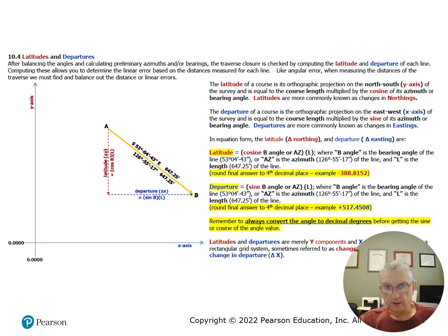So, here's just a good example. Don't round it too far. He's got, final answer rounded to the nearest 4 decimal places, and typically we'll carry coordinates to 3 or 4 decimal places, not 2, in our computations. Now, we may report to a lower order, but we want to carry them to 4 decimal places.